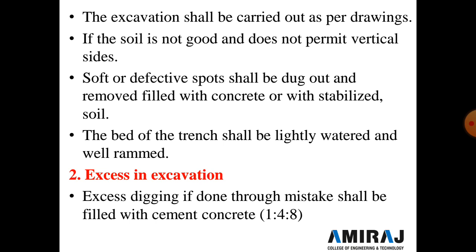If the soil is not good and does not permit a vertical side, the side should be sloped back or protected with timber shoring. Soft or defective spots shall be dug out and removed, and filled with concrete or with stabilized soil.